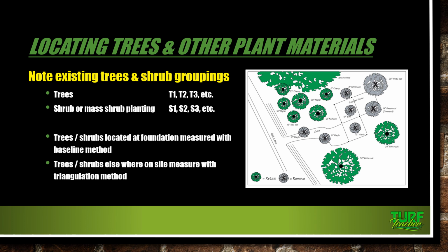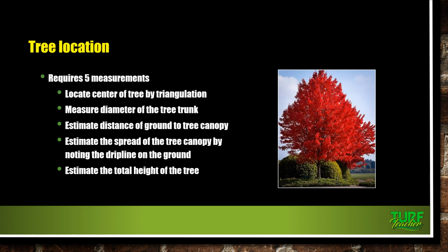Trees and shrubs elsewhere on the site measure with the triangulation method. And so, like I said, guys, if you're doing only that front foundation, that simple baseline is quick. You don't necessarily have to draw the full site plan if you're just doing a front foundation renovation, which is one of my favorites to do.